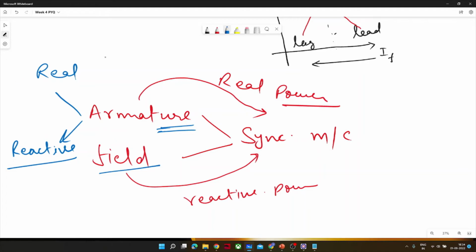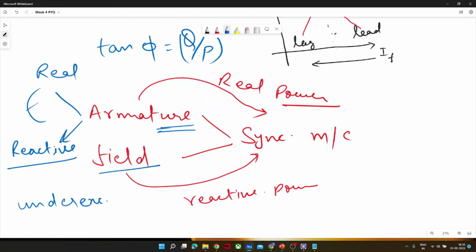So now we have some loss in power factor. This is Q by P. Some components are going into maintaining the rated flux in the machine, and the rest of the component is going to maintain the power. So that is the case, and of course, if it is the case, then it is underexcited and lagging power factor.